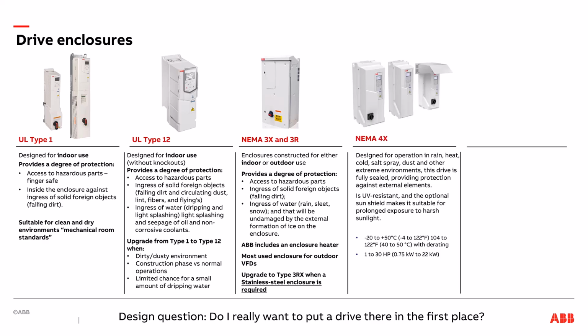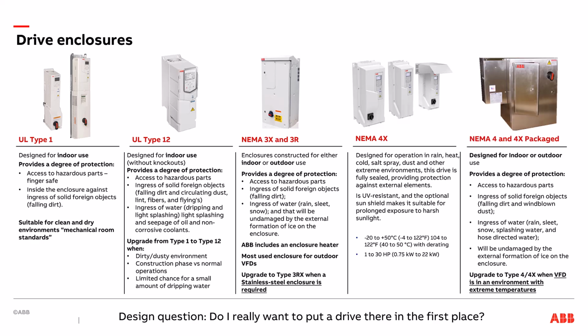Now we have the NEMA 4X, which is designed for outdoor or indoor applications. It can handle almost anything you throw at it, but should have a sun shield attached if it is going to be sitting in direct sunlight. Please keep in mind that this unit is not packaged with an air conditioner or heater, so derate conditions will apply to it. And last, we have our NEMA 4 and 4X packages, which are designed for indoor or outdoor use.